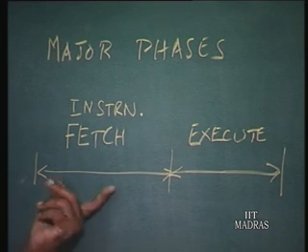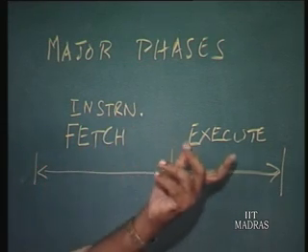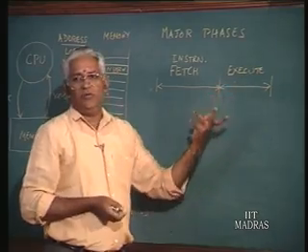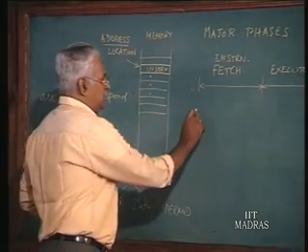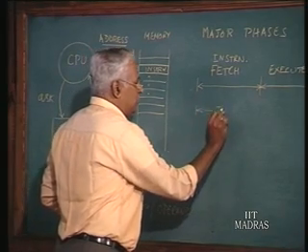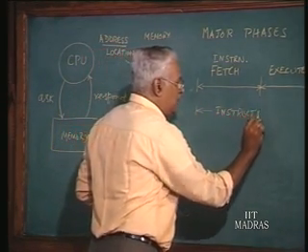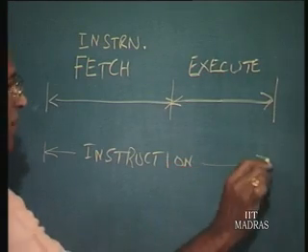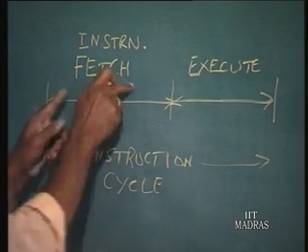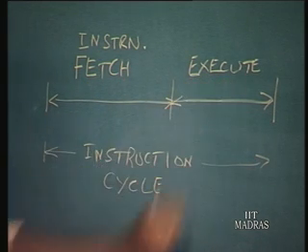So, instruction fetch and execute that instruction, and as I said, as part of execution of the instruction there may be data fetch or operand fetch also. So, this whole thing is called an instruction cycle. Now, precisely that is what the CPU always keeps doing, that is the instruction cycle consisting of a fetch cycle and an execute cycle.